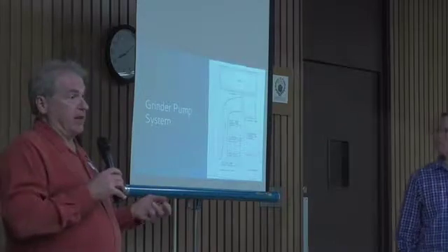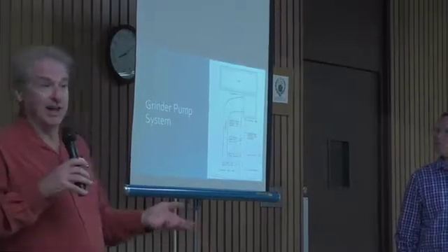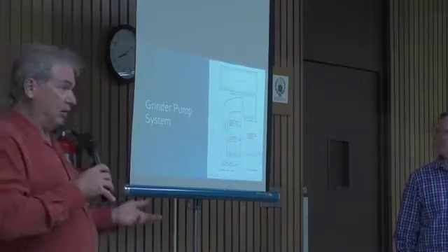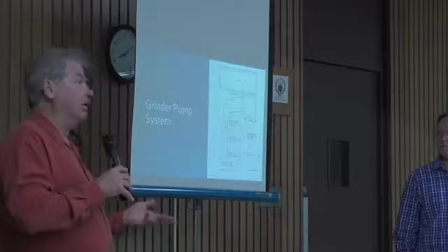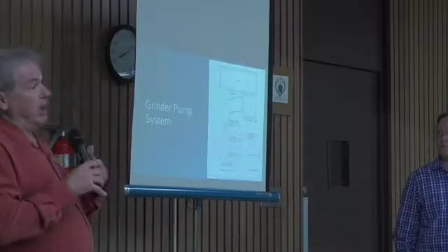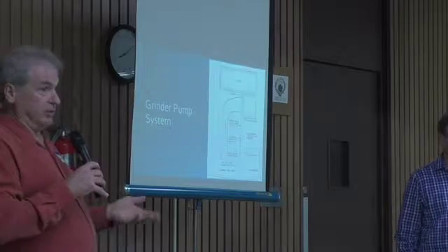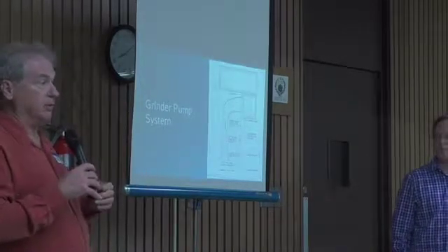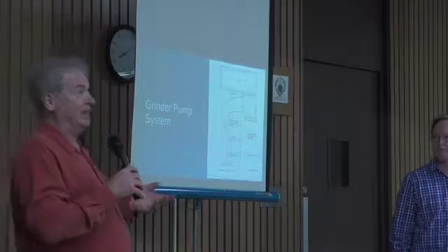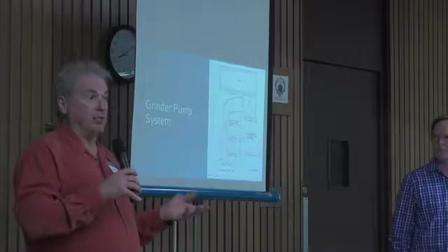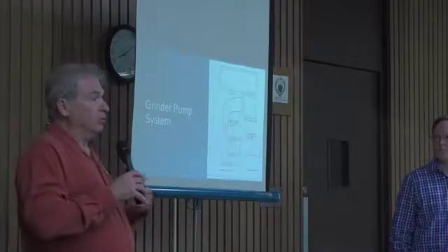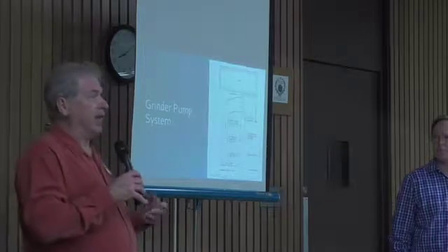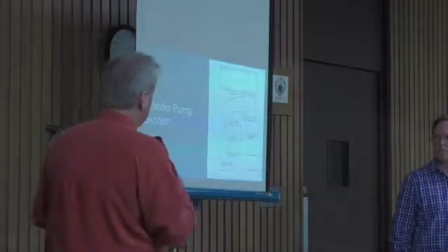Another disadvantage of the STEP system is you still have a septic tank, and it's still collecting solids, and still has to be pumped out at regular intervals. And when you have a community system, the every 3 to 5 year pumping cycle is strictly maintained, so that's a pretty costly endeavor to pump out that many septic tanks every 3 to 5 years.